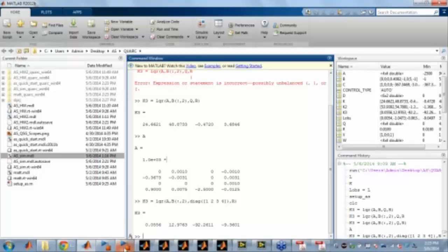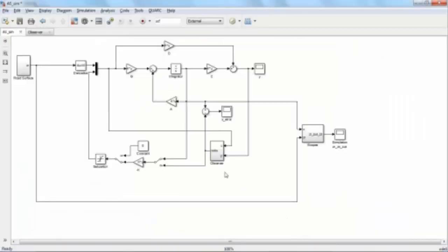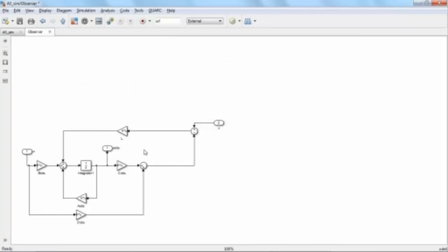And the way we do this is quite simple. We basically say, we know all this information about our system. We have this wonderful state space model of our system. How about we just copy this whole system, assume that it is a perfect copy of what we have, and simulate that perfect copy, give it the same input, and then use the difference between the output of what we think happens and what actually happens, send it through a gain, and make this whole system approach our actual states. And this is exactly what's happening here.